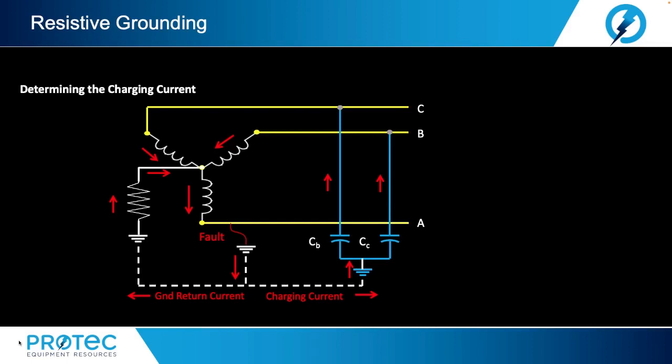It also recommends high resistance grounding be used only in systems of 5 kV or lower, charging currents of 5.5 amps or lower, and never in 15 kV systems. Now, a way to estimate the capacitive charging current for low voltage systems is as follows. A 480 volt system: 0.5 amps per 1000 kVA, or 0.5 amps per set of surge capacitors used.